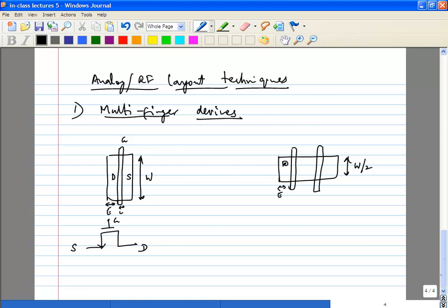Those are all things which are very important, and there may be cases where you really want to widen out this E, because if the transistor is operating at a very high current density, you might want to have more contacts. By the way, contacts also have current density requirements. So you may want to have more contacts in some cases, but in most cases, let's just consider this.